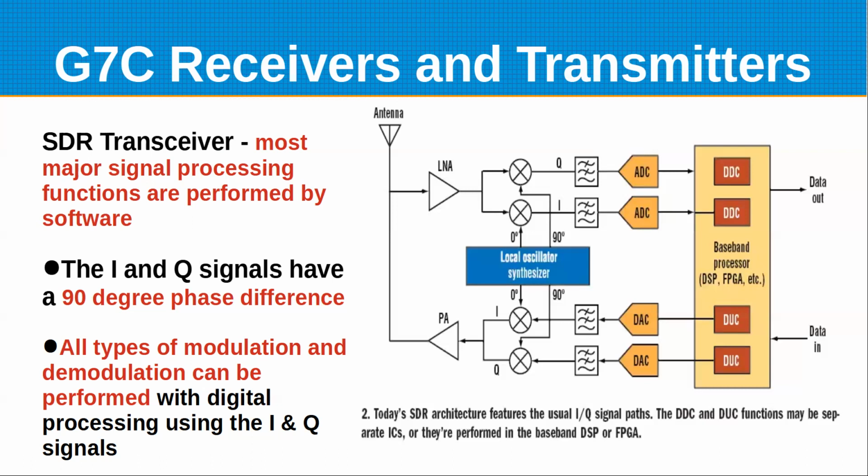So we'll get a sine wave out of there, which I can combine the I and Q and actually wind up with an RF sine wave, which is only the sideband at whatever frequency we're transmitting.